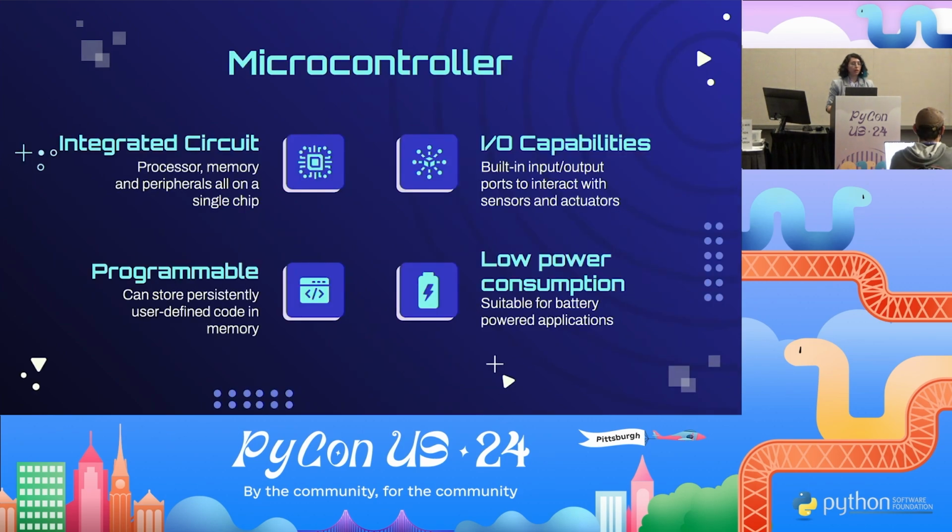So a microcontroller is a device, just like the ones we have here. And it contains an integrated circuit. So it has a processor, memory, and peripherals all on a single chip. And it usually has some I/O capabilities. So you can connect the device with sensors and actuators, so you can interact with the physical world. It's also programmable, so you can change the function of it with your own code. And it usually has lower power consumption, so you can use batteries to power it. So here we have a pack of AAA batteries, there is enough to power the microbit for a few hours.